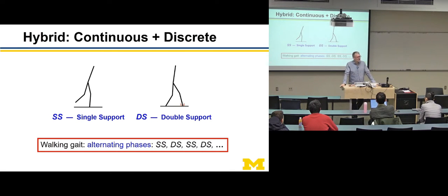How much time do you want to spend modeling something that's that short? So you could just take that limit and make it 0, and then the force becomes an impulse. If you take a second order linear dynamical system, like a double integrator, and put an impulse into it, you get a jump in the velocity and the position stays constant. Go home and check it with your Laplace. You can do the same thing with these nonlinear robot equations.